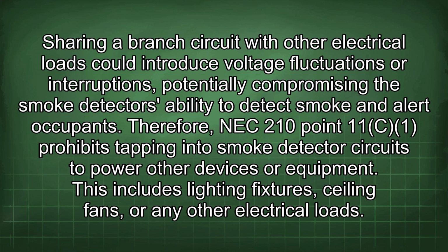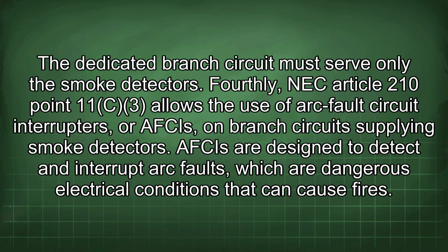Therefore, NEC 210.11(c) prohibits tapping into smoke detector circuits to power other devices or equipment. This includes lighting fixtures, ceiling fans, or any other electrical loads. The dedicated branch circuit must serve only the smoke detectors.